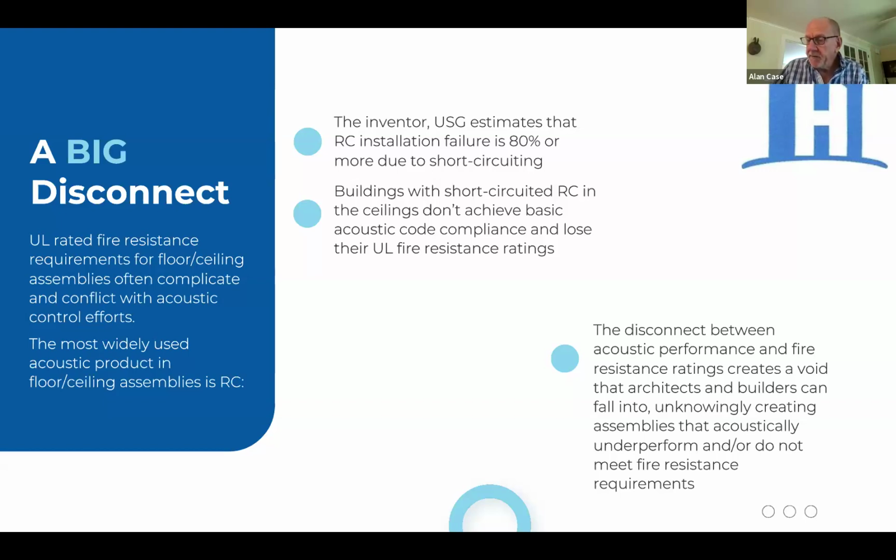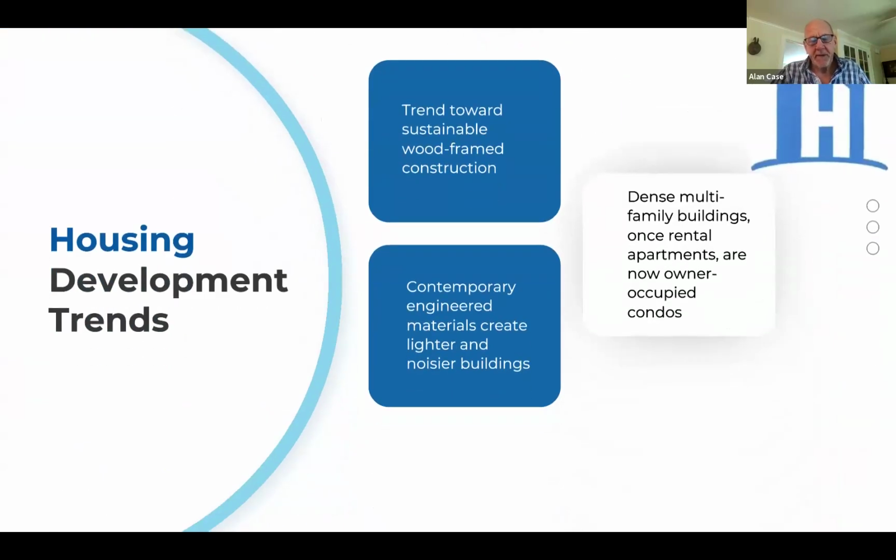If you have insulation material that's over 3.5 inches, that's not stapled to the underside of the floor, you'll have an issue with UL. They require that any insulation greater than 3 inches be suspended in the center of the bay.